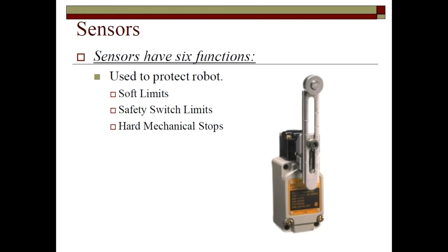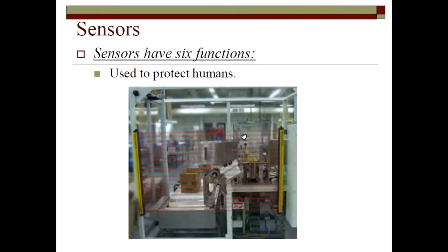And then when you activate the switch, you're actually breaking the connection and sending a 0. Okay, so normally closed would mean that we're sending a high signal into the controller. So if we go back and look at this, emergency stop type switches are wired as what we call normally closed, which means that we're looking for a 1. So this has got to be a 1 here.